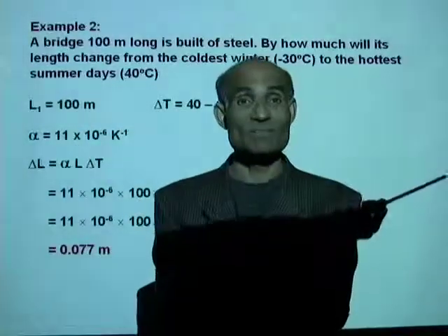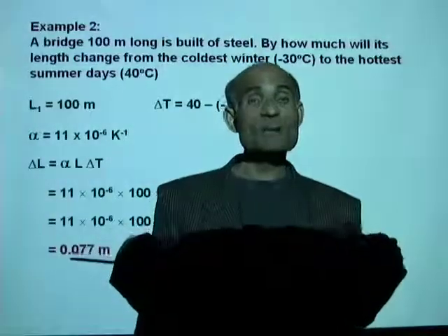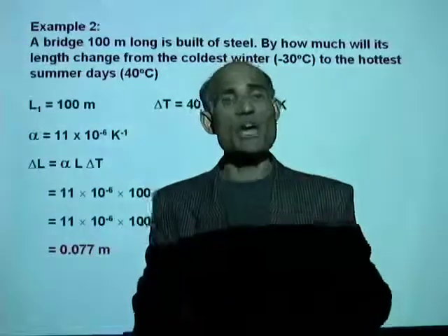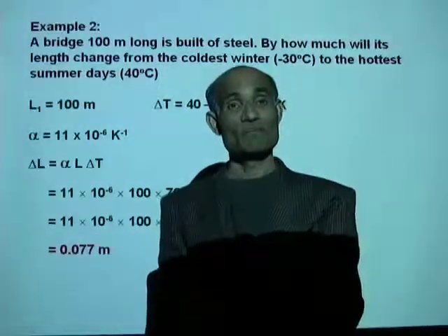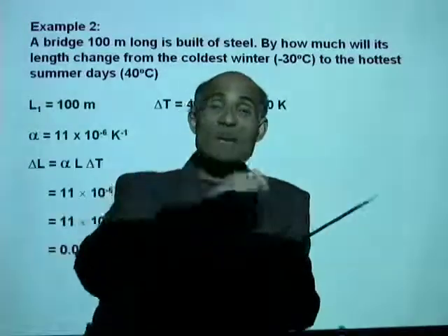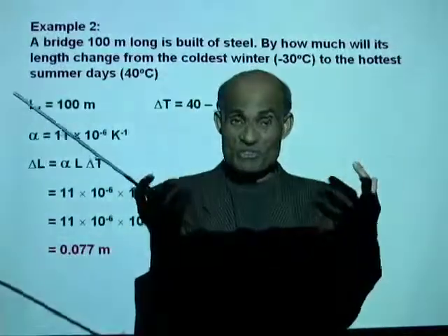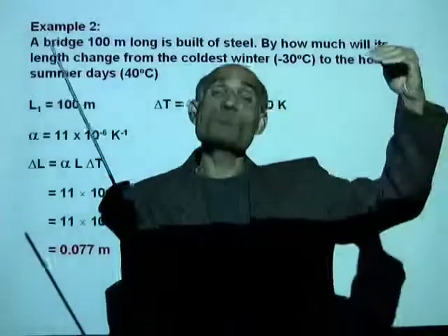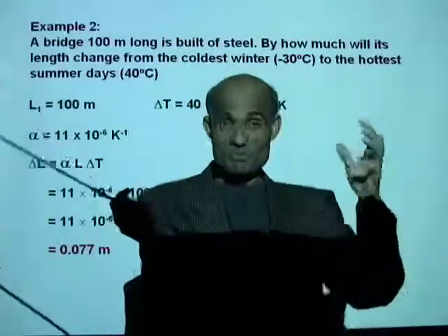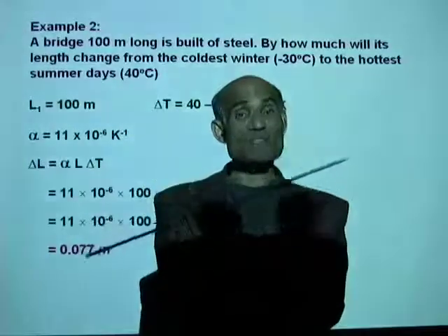If you look at your driveway, when concrete slabs are placed to build your driveway, do we make one full concrete slab for the whole driveway? No, we don't. We break them into slabs and allow a space between them. Why? Because when temperature increases and decreases, from cold winters to warm summers, there are tremendous changes in temperature, especially in Florida. That means the concrete slabs will be expanding and contracting.